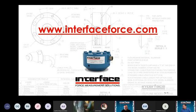What is the standard range of application for a standard load cell? That is wide. I'm not sure I can answer that, Alejandro. It's going to be a function of the environmental requirements and the force requirements, but most of our standard load cells would be good for indoor lab testing and occasional outdoor use. If it's going to see sustained outdoor use or potential rain or moisture, we'd have to move into either specific option codes for those units or different units altogether.